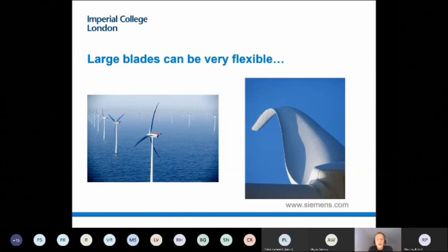However, as you go higher in the atmosphere, the wind speed is faster. Wind turbines are all by definition in the boundary layer of the atmosphere. A boundary layer is a situation in which the wind speeds are decreasing. So one reason wind turbines get taller is that the taller you are, the faster the winds, to some level. Typically the atmospheric boundary layer is about 400 to 500 meters. So we are not quite there yet. So there's still growth potential there.